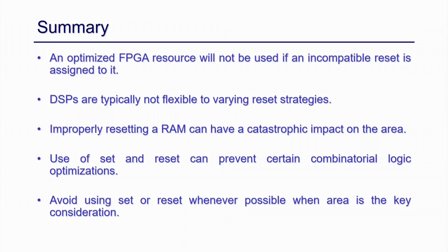You should not use asynchronous reset or synchronous set for DSPs, and as a whole you should not use reset for RAM. Specifically, you should not use asynchronous reset for RAM, because it has a very catastrophic effect on area and performance. Also, for flip flops you should usually keep the reset and set pin open, so that the synthesis tool can map certain logic as a reset or set, which gives a better area benefit.